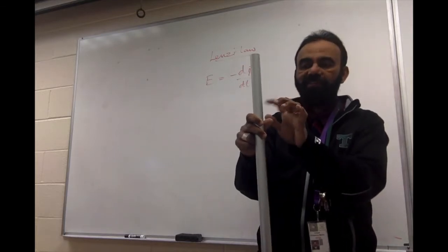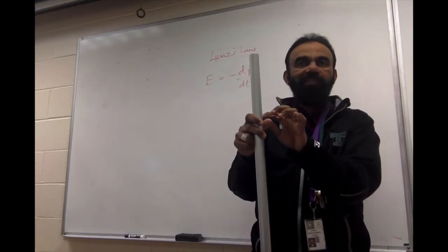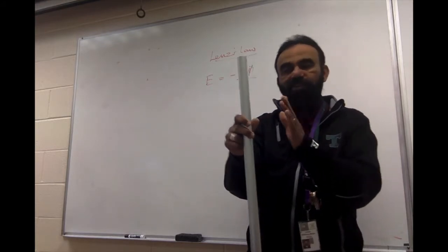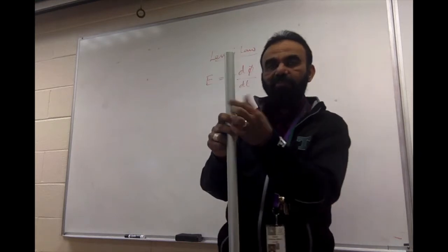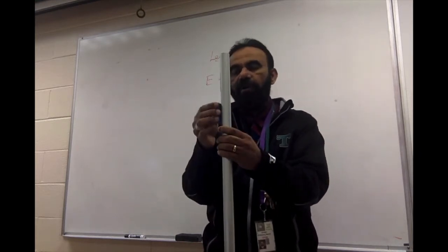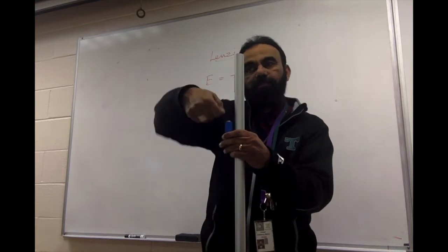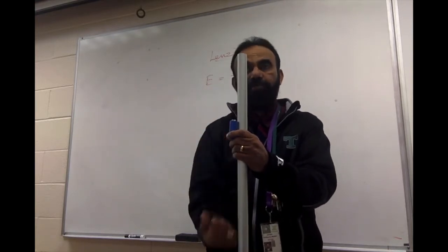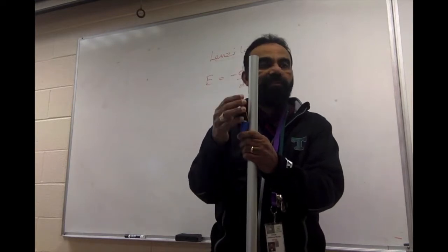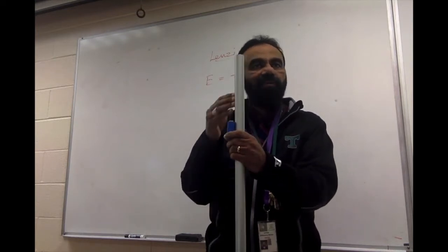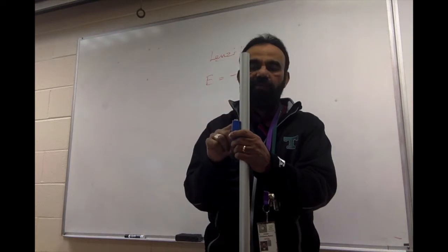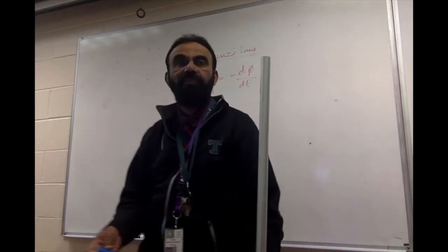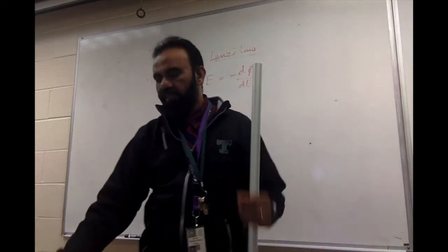But then you cannot have it this way, because it has to be separate coils, and the coils must be all separate segments. Because if you are actually making current flow one way, the object which is going down can be pulled in as well. So if you want to accelerate it, you need to pull it down with a larger force. And that means you need to make the current flow differently as it goes down. It needs different coils, and it's not that easy.